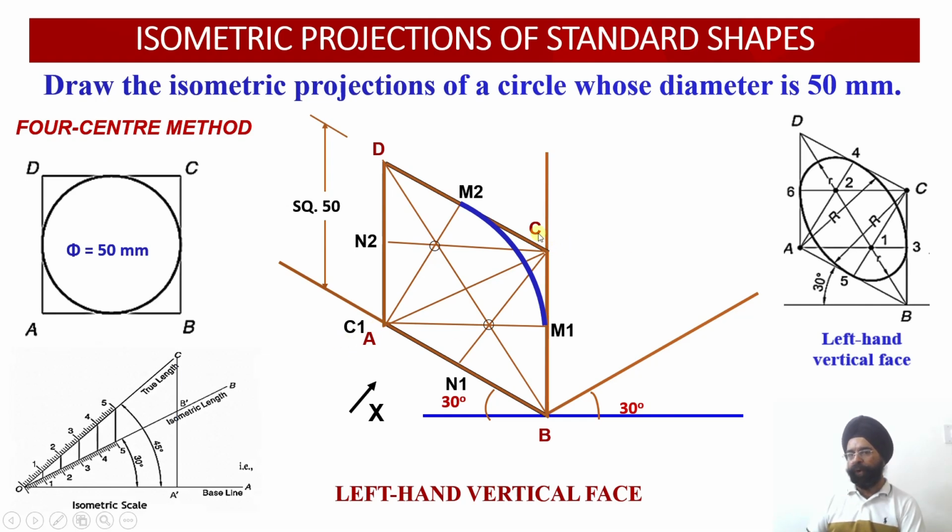Similarly, I have moved to point C now. This is my second center. So from the second center, once again, keep the needle of the compass here. Open compass equal to CN1 and equal to CN2. So the radius will be the same. So open your compass from point C, needle will be here, and this will be your pencil point. Again, using the compass, draw one perfect arc joining C with N1 and N2. So the 2 arcs for the ellipse have been drawn.